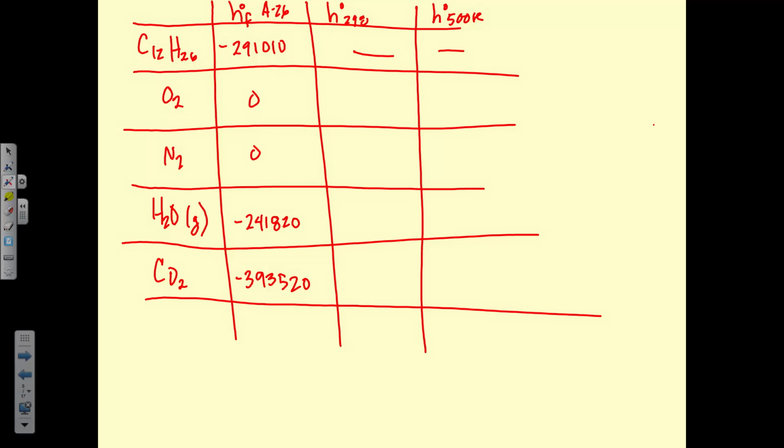So then we look up the reference enthalpy for oxygen is 8682 at 298 Kelvin, so we get that from table A19. For nitrogen, it's 8669, that's from table A18. For water, if we're treating it as an ideal gas vapor, it's 9904, that's table A23.